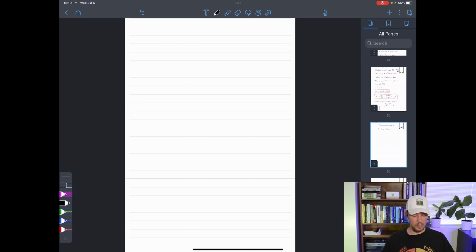All right, guys, so in one of the last videos that we covered, we went through and found a Thevenin equivalent circuit for a circuit that contained nothing but dependent sources. The same method of finding the open circuit voltage and then finding the short circuit current and then using a few extra equations, that same method can be applied to find the Thevenin equivalent circuit for a circuit that contains dependent sources as well. However, I really want to get very concrete and go through a particular example to show you how you can use these same concepts to find these Thevenin equivalents.